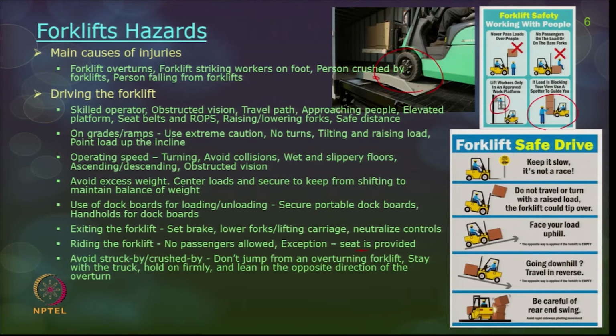So, forklift safety again: always keep it slow whenever you are moving in congested sites. Face your load uphill, and when you are going downhill, you should travel in reverse. Always the load should be pointed only in the upward direction. Do not travel or turn with a raised load. Always lower the load when you are turning or traveling, because it may tip the forklift over. Be careful of rear end swings.